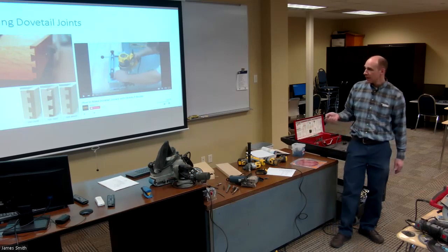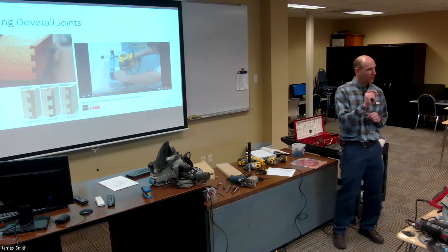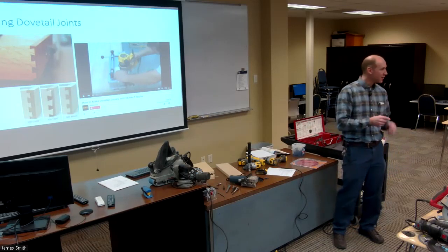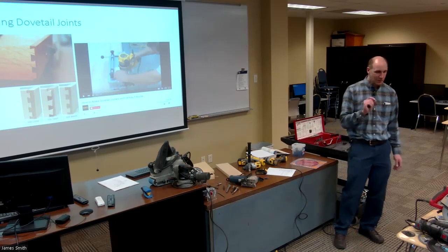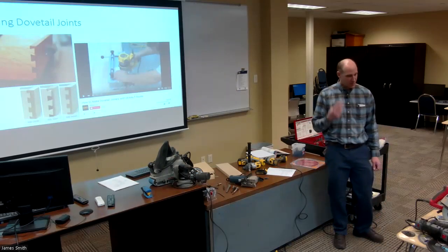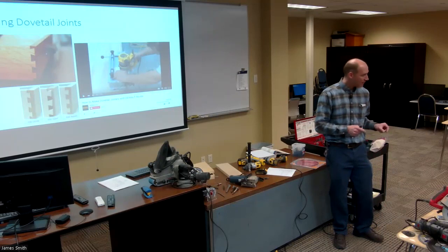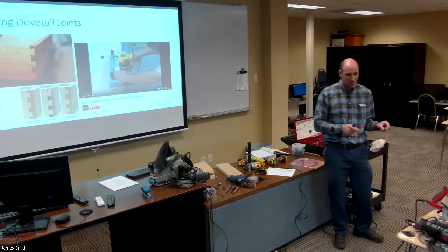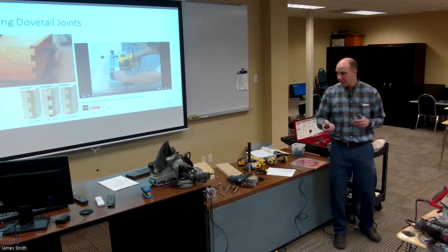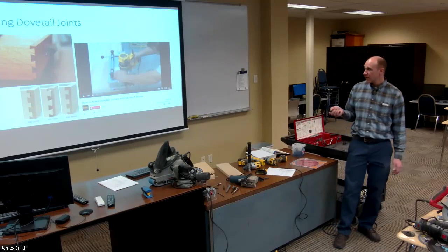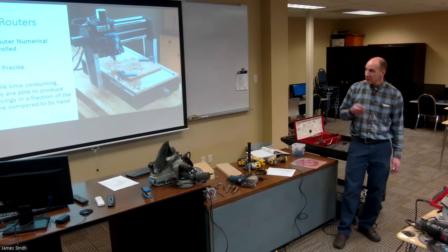And so it's also a matter of the thickness of the material. We try to only dovetail drawers that have 1/2 inch thick drawer sides, and so then we can maintain and keep a standard setup on our router jig that way.